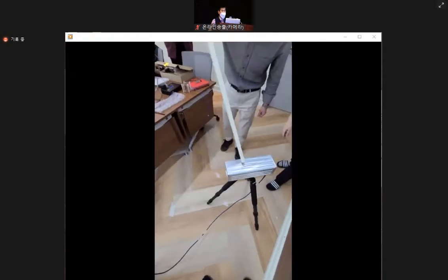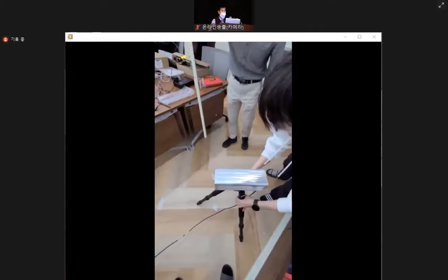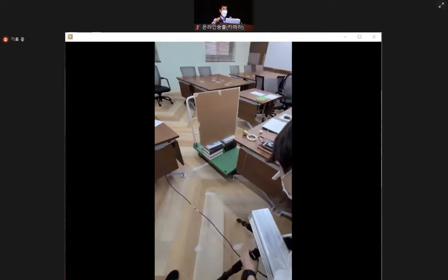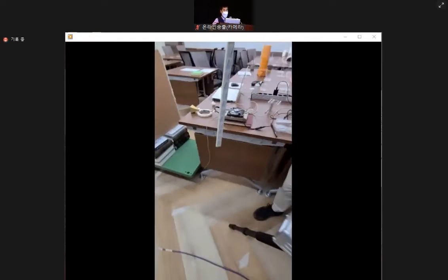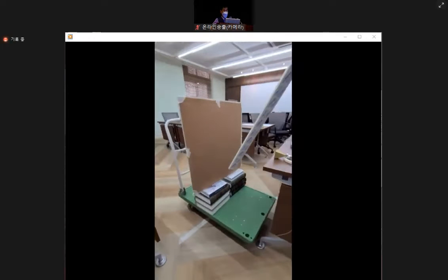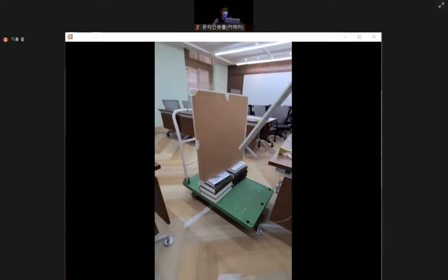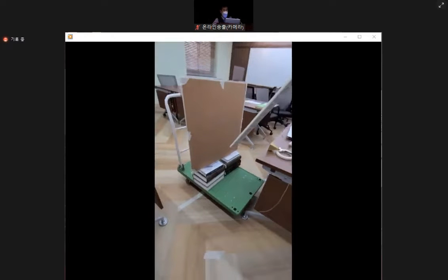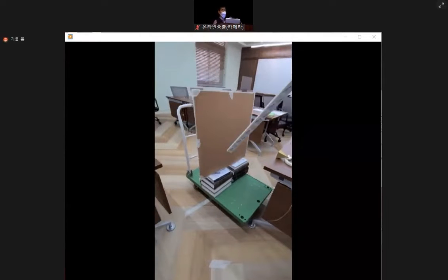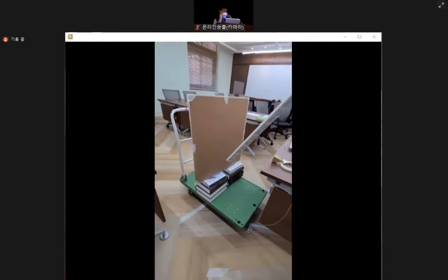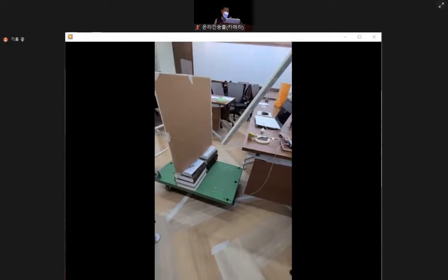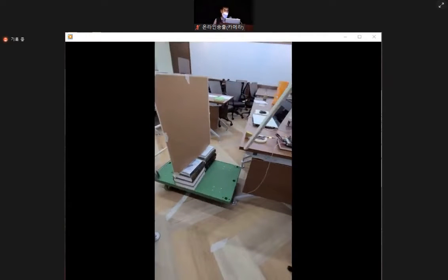So please move this to a lower angle like this. How about this? To a lower, I'm sorry, one upper angle, a lower angle, but to this direction. As you remember, in the previous test, at a little bit lower angle from the 41 degrees, such as 20 degrees, the signal strength was not ignorable. Why? I told you the near zone area is polluted with a lot of noise. So it is hard to distinguish the observation from 45 degrees to 20 degrees. We expect the intended direction of reflection and the decrease of signal strength of the received power.